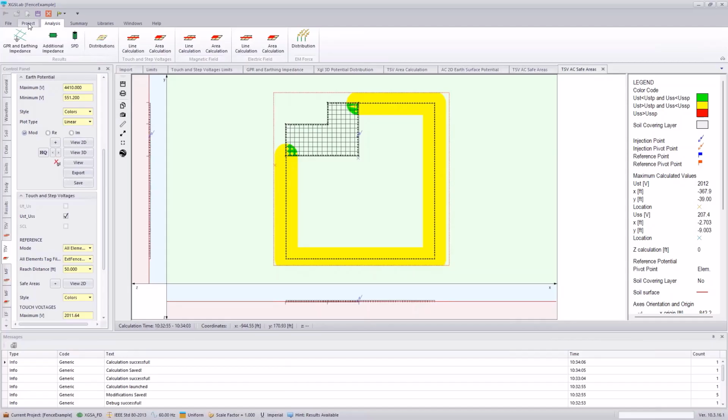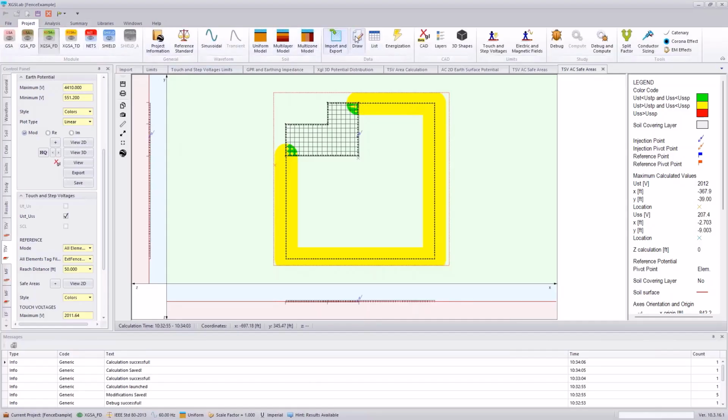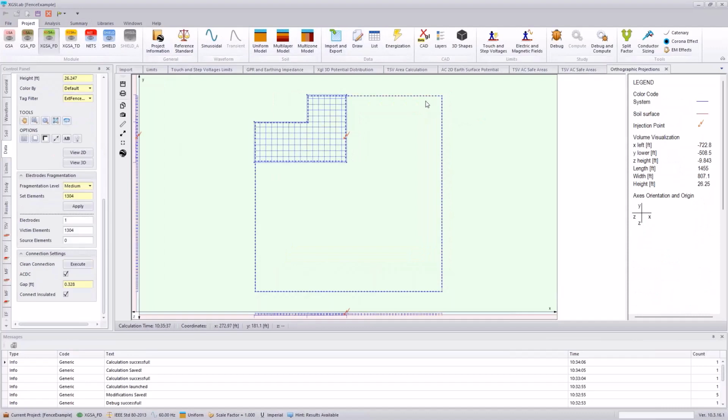And one methodology for that is, if this fence is a perimeter fence for non-essential equipment or something that's not high security, we could recommend mitigation with a wood or non-conductive fence type. And we can do that strategy simply by going into my model, and I'll zoom in here so you can get a little better view of this.